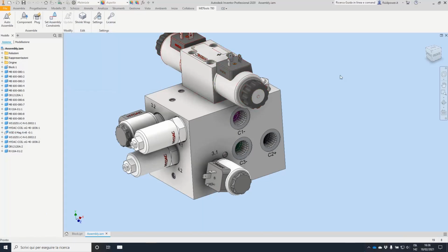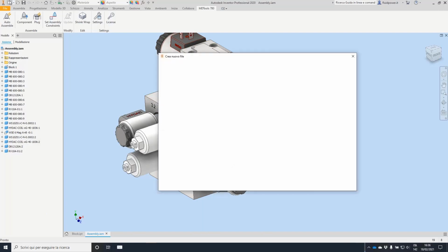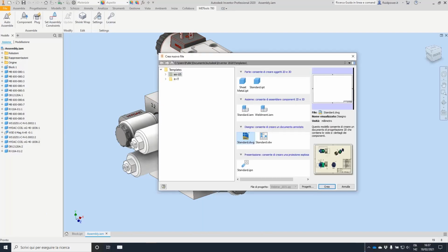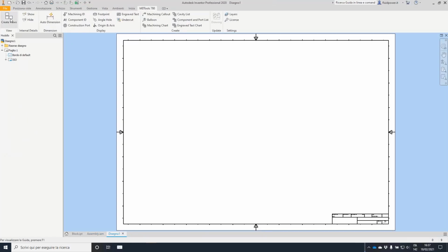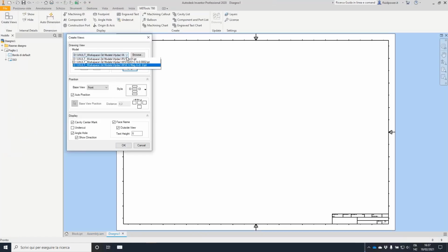It's done. I'll open it later with SolidWorks to show you the internal, but now I also want to make a machine drawing of the block. So I create a new drawing. I will place the 6 views of my block, and I can decide where to put the 6th view. I want it on the right.